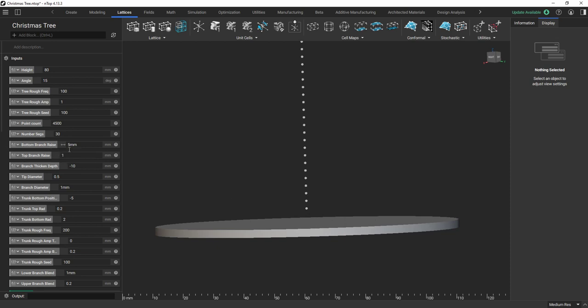Right now it's set to 5 millimeters, so it's 5 millimeters higher. If that was set to 0, the branches would all orient at the same level as the branch tips. Then we'd of course run into that problem with 3D printing. The angles would be all wrong.